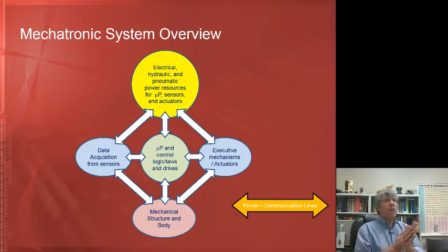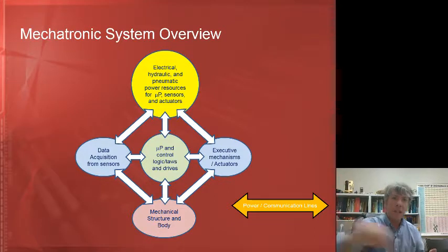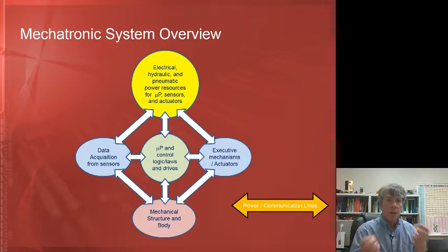You see, we're going to use Arduinos, but for example, we can use a computer as an example. You would never expect to plug, say, a big industrial motor directly into a computer and the computer just drive it, right? That doesn't work. The signals that come out of the computer via ports or even wireless signals are very small scale. They don't have much power. They can't drive a big motor.